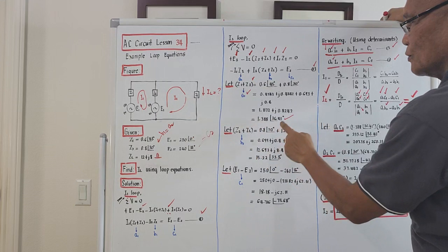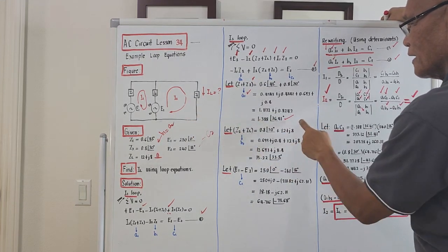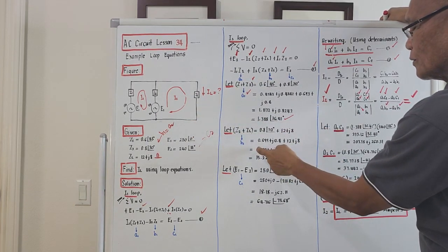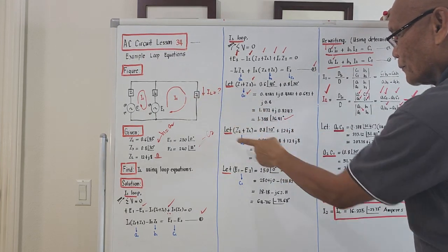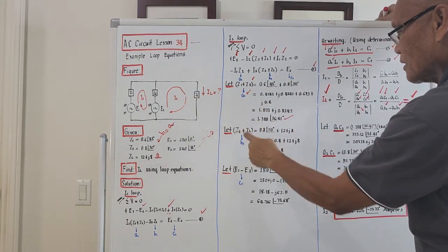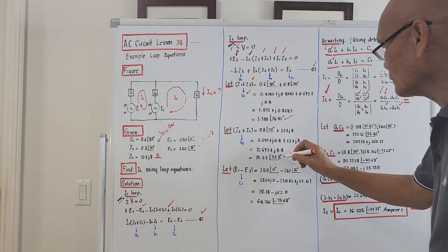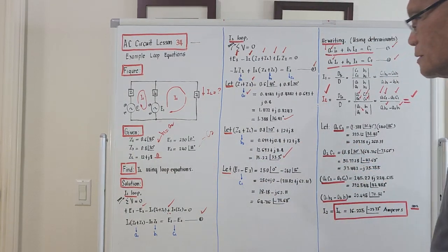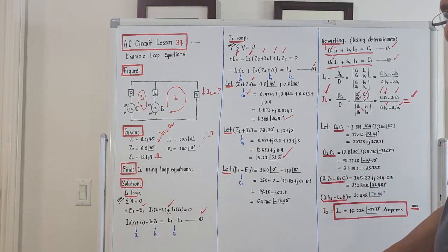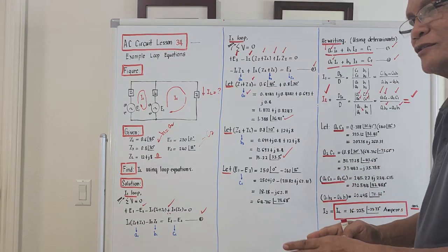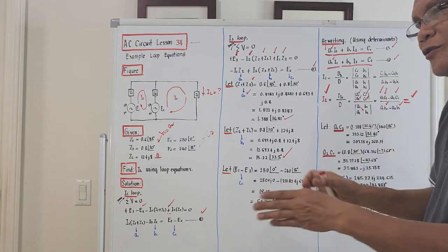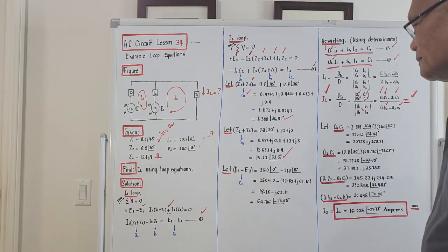We are given C2. We are given CL. Converting to rectangular, then converting again to polar, the polar equivalent of the sum C2 plus CL is 15.22 angle 33.5 degrees. We are just being systematic and taking it easy, okay? You cannot accelerate in the solution here. Just take your time and be accurate.